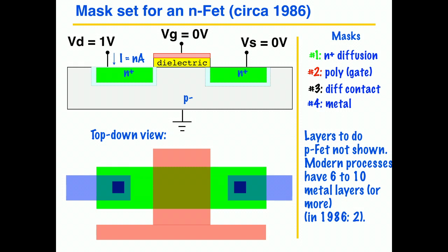Usually when we lay them out for purposes in the circuits, we know which is going to be the source and which is going to be the drain. And for NMOS transistors, this type of transistor, almost always the source is connected to the ground, the low voltage, and then the drain voltage is used for connecting to other transistors, as we'll see. But as far as the physics, it doesn't actually know the difference. It's just which way you bias the voltages that makes the definition of which one's source and which one's drain.